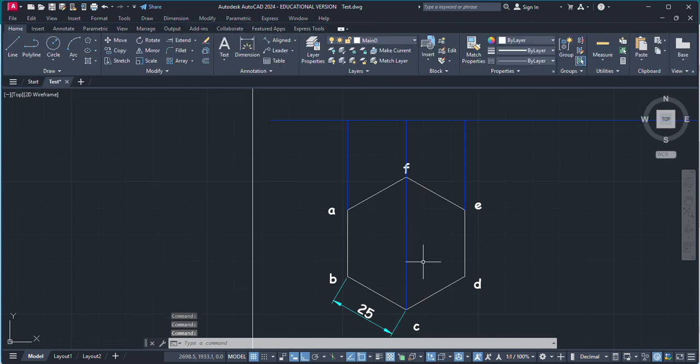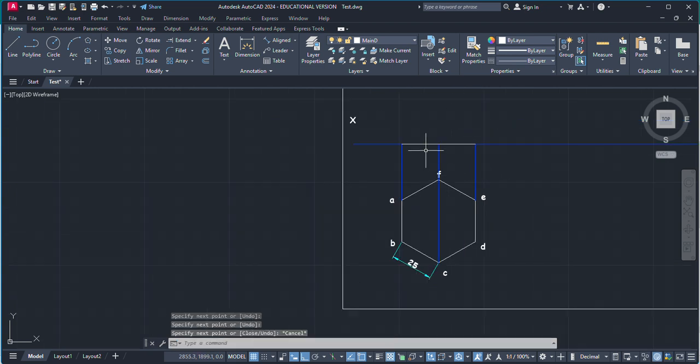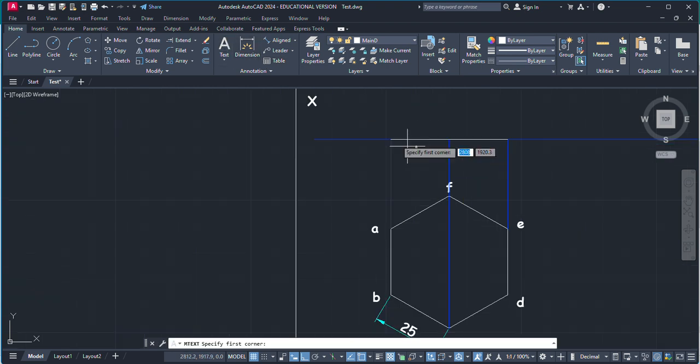Again, when we observe this plane from the front, a straight line will appear because it is resting on HP. So this front view will appear on the reference line. It will start from here and end here. Again, I'm going to take this in multiple segments, from here to here first, then here second. Now name them.